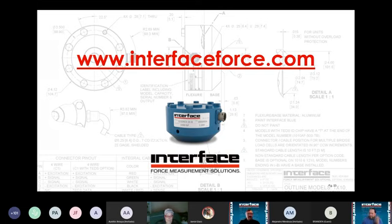Great. Another question coming in with regards to a better way to tare a load cell, whether to do it by electronics or mechanical preload. Taring of the system is typically done through the instrumentation. You would just want to ensure that whatever mechanical tare load you have on the sensor isn't going to impede on your usable capacity range. But as far as the load cell is concerned, really no need to accommodate any sort of mechanical tare. These are linear devices as long as you're staying within the range.